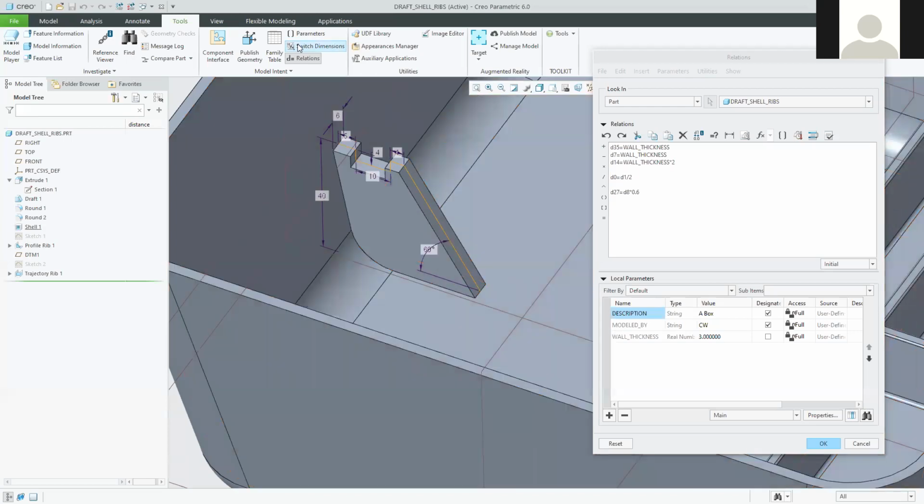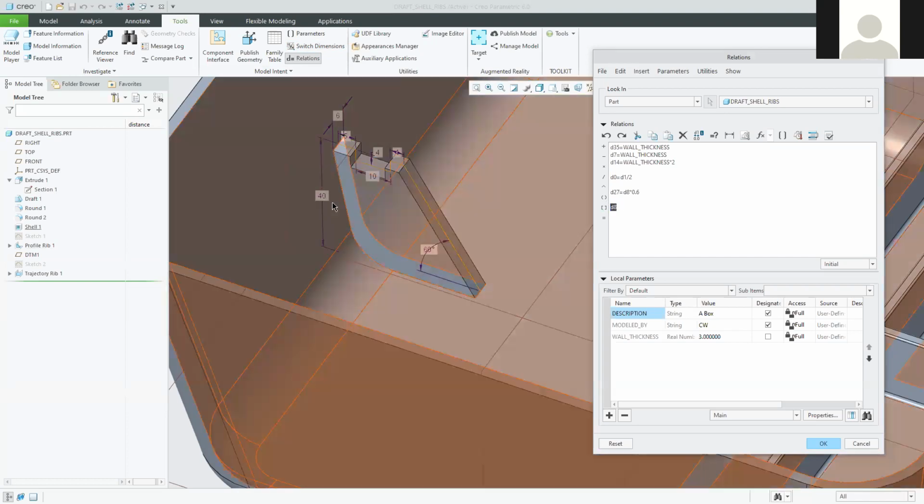And what that does is it toggles between the labels that the system gives everything versus the actual dimension values themselves. But if I click on them, it still collects it as the label that the system has given it. That's just for me as a human to be able to read them a little bit more logically, so I can spot the dimension that I want.